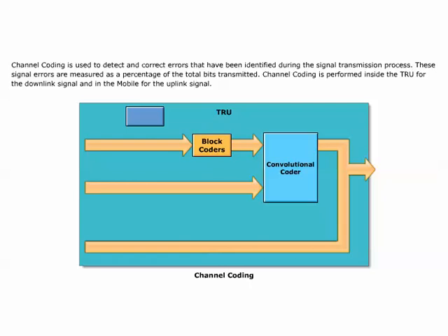The speech coder delivers 20 ms slices of speech containing 260 bits of speech information. The 260 bits of information is divided into 50 very important bits, 132 important bits, and 78 not so important bits. 3 parity bits are added to the 50 bits, block coding. These 53 bits, together with the 132 important bits and 4 tail bits, are convolutionally encoded to 378 bits. The remaining bits are not coded.